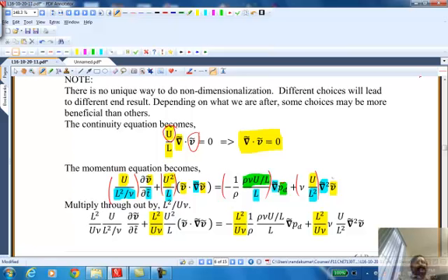What is the reason for making these dimensionless? Of course, first they are dimensionless. The other one is the magnitude of them will be of the order 1. Okay, because whatever the velocity is, I'm scaling with respect to u. Now, u, for example, in a tornado could be 150 miles. So when I scale them up, all the scaled velocities will be of the order of dimensionless unit 1. Okay, whereas in a microfluidic device, that u, the mean velocity, could be of the order of so many micrometers per second. Then once again, I'm not dealing with extremely small numbers. When I scale it up, I'll get numbers that are between 0 and 1.